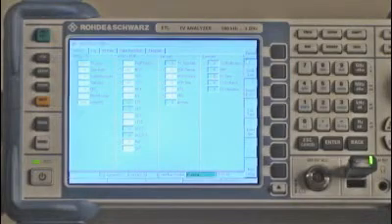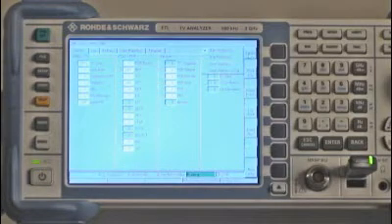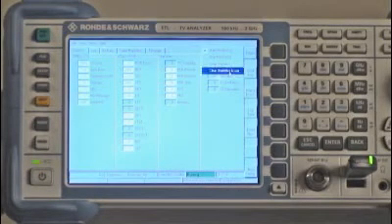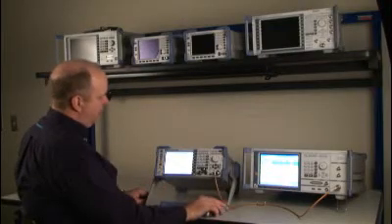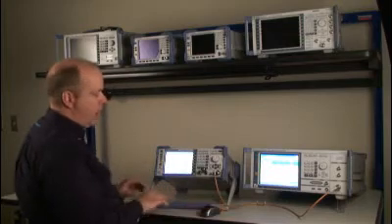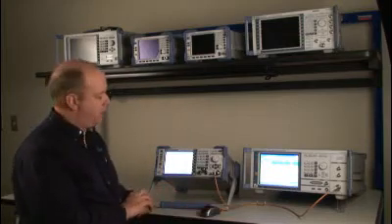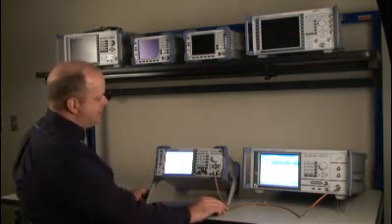So what I'm going to do is go into the control, which is on the right hand side top of your screen, and clear statistics and log. This will reset all of the measurements and all the log, and I'll come up with a total of 0 errors, as long as there are no errors within my transport stream.